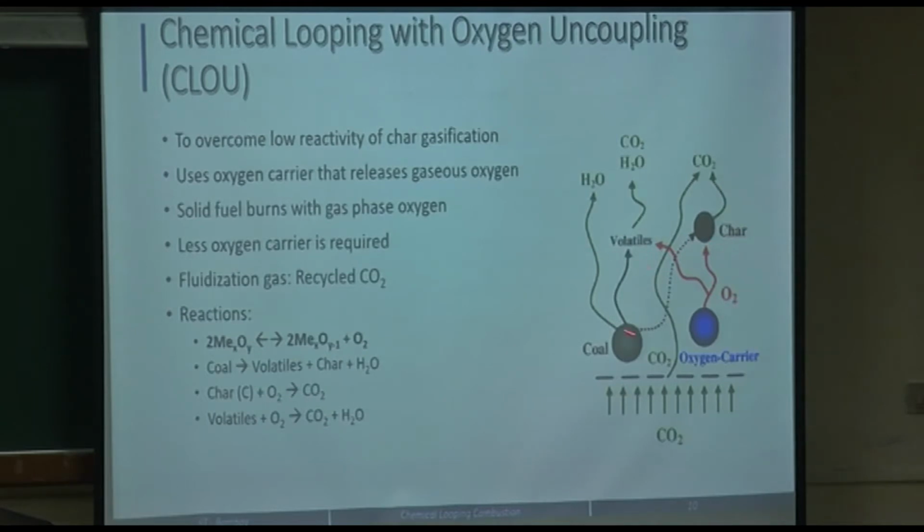So the conversion is more in this case, but the problem is that these oxygen carriers are highly costly. And if there is ash deposition or even char deposition on the oxygen carrier, that would reduce its efficiency. But less metal oxide would be required in this case, because the conversion would be more, since the solid fuel burns with the gaseous oxygen as opposed to the previous case.